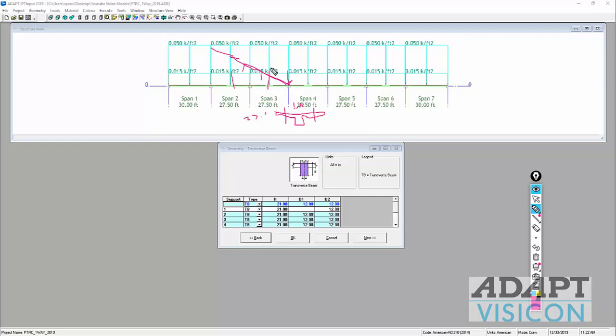In this case, the beam spans are going to be 34 feet. We're going to do a 34 foot, a 28 foot, and a 34 foot span. So we have a 3-span condition. We're going to assume that the columns are 24-inch square columns, 10 feet high. That's the height of the column, and we're going to check the beam design with columns below the structure versus below and above. So there's options for both. We're going to assume only supports below. Okay, so that's our summary for this tutorial.